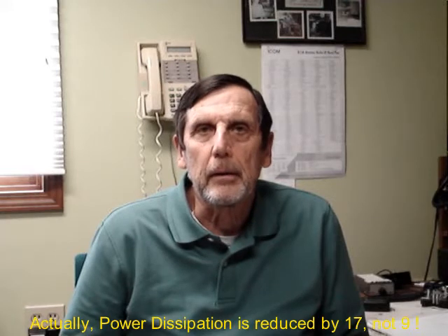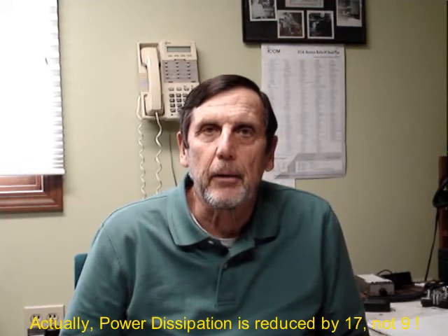First of all, what exactly does the electronic bias system try to do? Well, when you're normally at very low levels, your amplifier will draw a very slight amount of current. For instance on an SB220, the idling current, rather than being 0, might be like 7 milliamps as opposed to the normal idling current of over 100 milliamps. So if you calculate the power dissipation at 7 milliamps versus 100 milliamps, you get well over about a 9 times reduction in idling power. So that causes everything to run cooler.